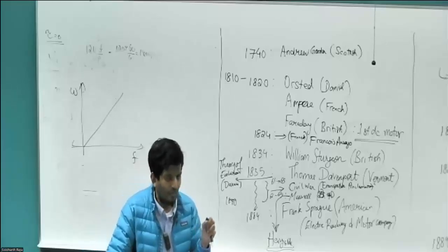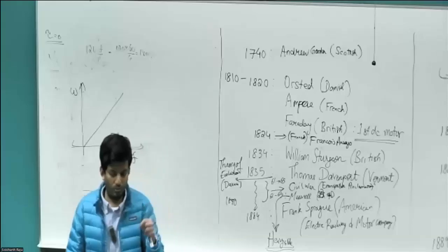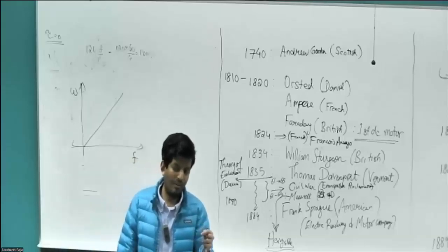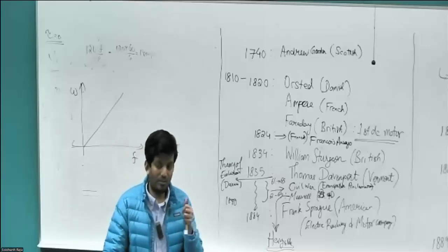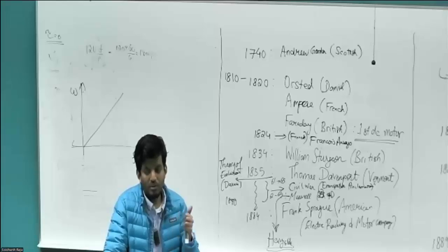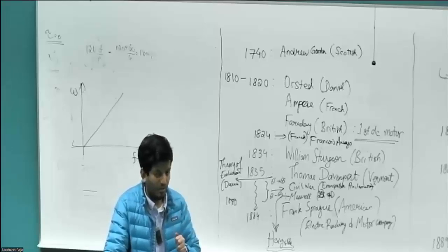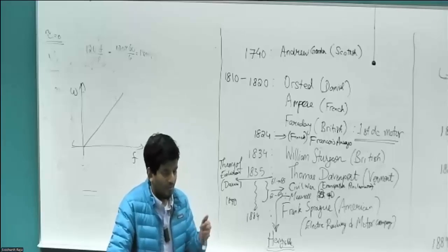And when this happens, if your rotor magnets are aligned in such a way that the flux produced by the rotor magnet is opposite the flux produced by the currents flowing in the stator winding, the flux due to the stator current flowing in the stator winding can end up demagnetizing the rotor magnets. So this is a very huge problem that could not be addressed properly without use of power electronics.